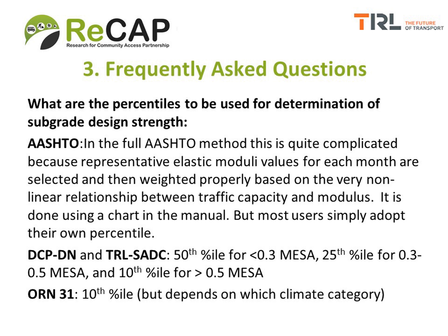It's not very difficult to use because the AASHTO manual has a chart that essentially does it for you, but many people think it's too complicated. You don't need to be quite so inventive, and most people simply adopt a lower percentile representing not the average subgrade strength, but the lower 10 percentile or the lower 20 percentile. It's much easier to do that, and most people understand that. So that's what I would recommend you did.